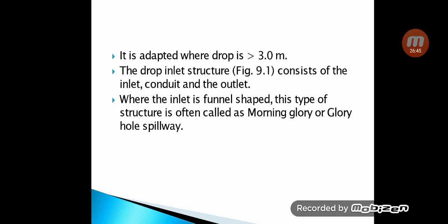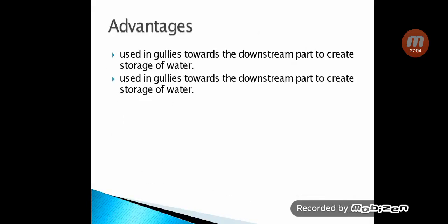So it is adopted where the drop is greater than 3 meters, where the drop height of the water to be discharged is greater than 3 meters. The drop inlet structure consists of inlet, conduit and outlet. So these are certain advantages.